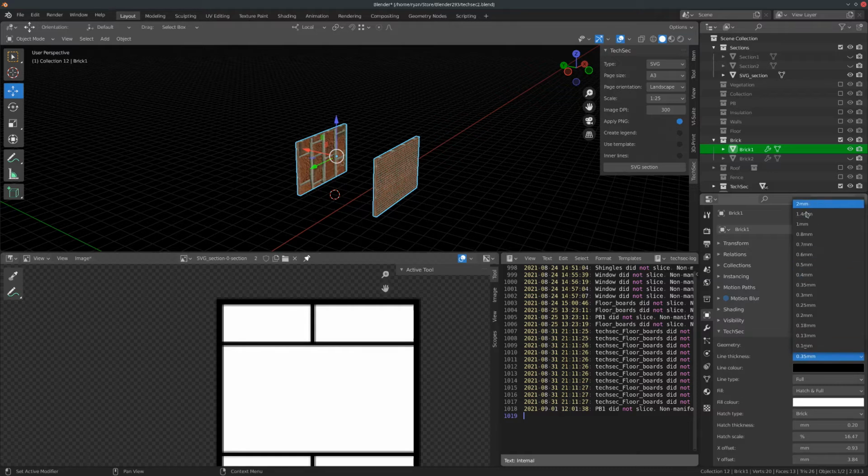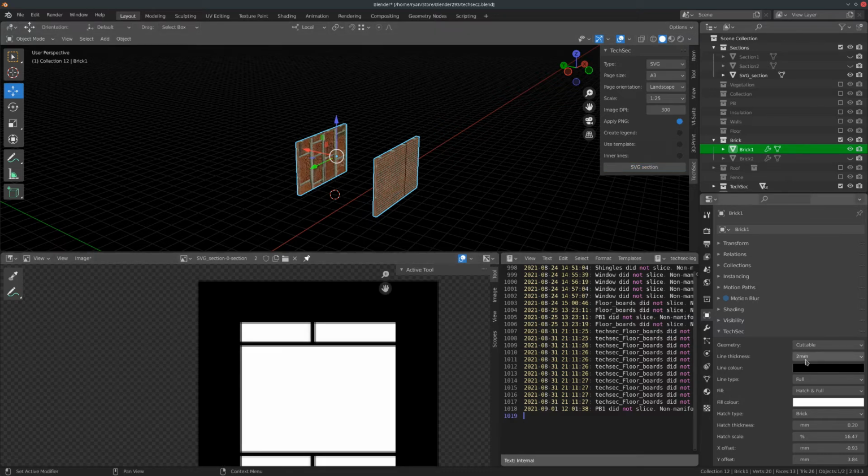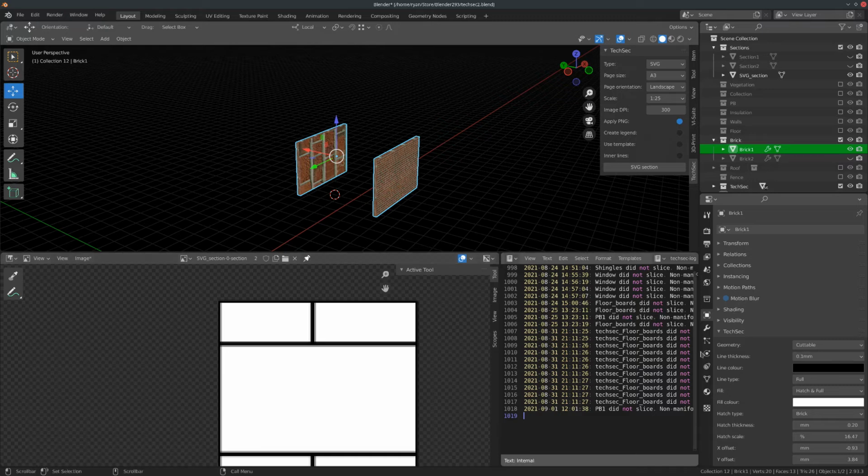And we have here all the standard, certainly architectural, line widths, and I guess it would cover a lot of engineering line widths as well. So I can make that 2 millimeters. We get a 2 millimeter line, 0.1, you get a 0.1 millimeter line. So let's put it 0.3.